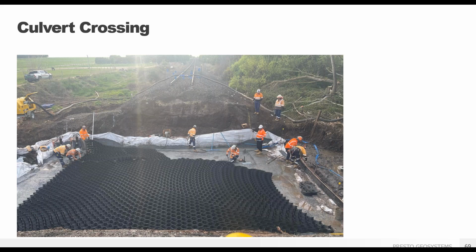So we worked with the engineer of record and also the geotech to come up with a couple of different analyses. We conducted several design evaluations and determined the necessary working platform thickness to achieve the necessary bearing capacity. Our proposed solution included multiple layers of geosynthetics. You can see in the photo here, we used an enhanced woven geotextile, here's the white layer. On top of that, we added a biaxial geogrid and then 150 millimeter GeoWeb.